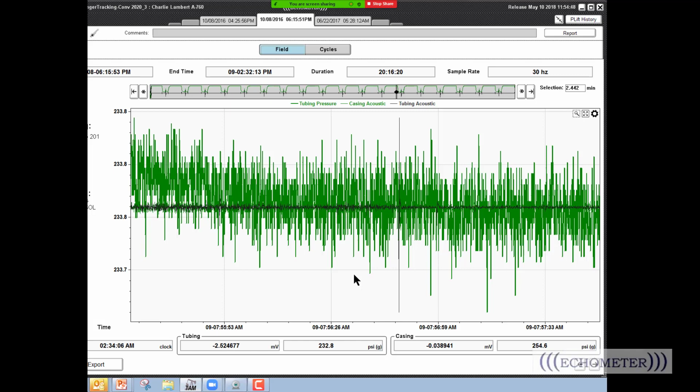It's also a function of the seal, so if you have a very corroded area of pipe, the seal is going to be poor, and the plunger is going to speed up. So the plot of plunger velocity would be an indication of two things: gas flow into the tubing and seal or corroded tubing.